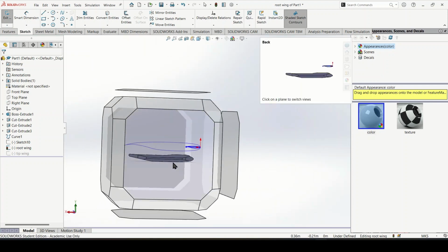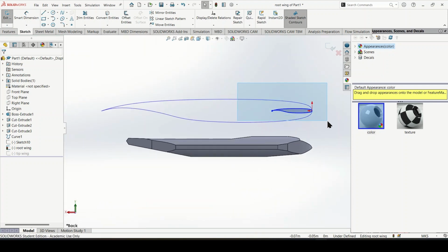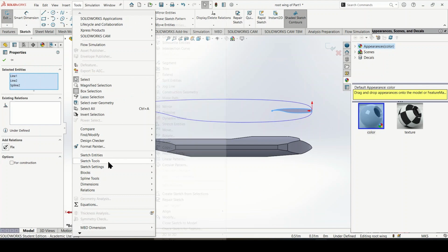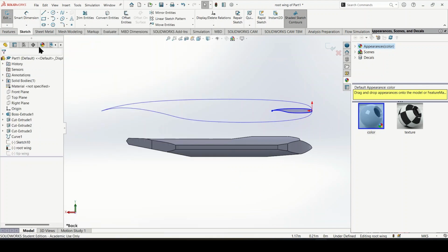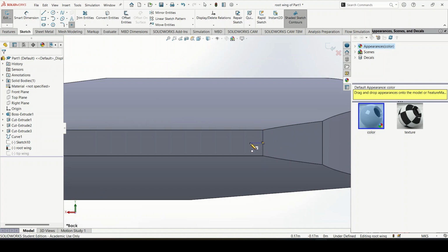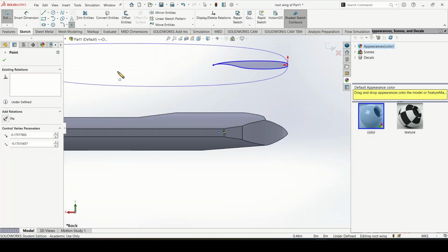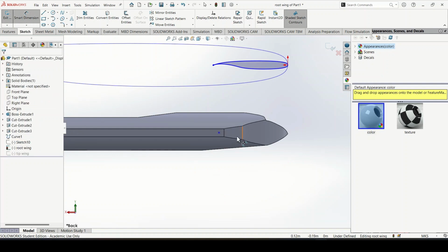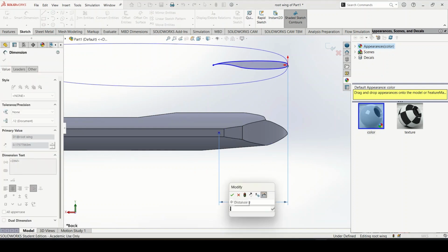And if we move over to this plane, we can then do the next step, which is to move it. So, I want to create a dot roughly in the center, and we want to put it 268 millimeters behind the origin. So that's 0.268.